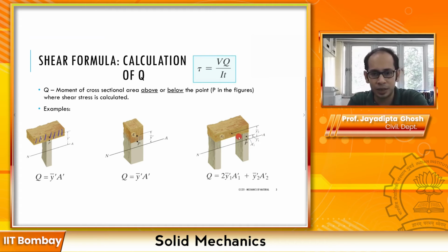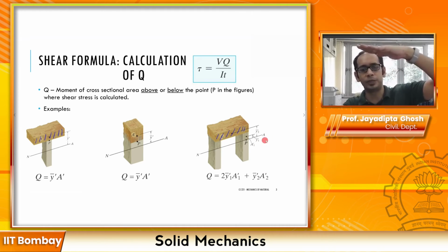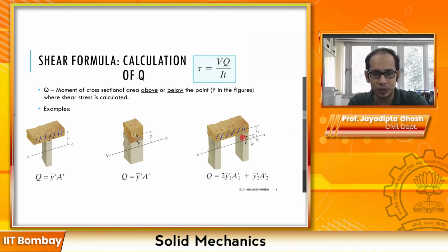But anyway, regardless, to calculate the Q here, you can separate this into two chunks. This is essentially how you calculate centroids of sections and so on. So you can consider this area, that is your A2, and because of A2 the distance of this one is y2 bar prime, and you have two smaller areas over here. So you essentially are taking the whole area above this line, which is parallel to the neutral axis that you have over here. So you are taking these two areas as well.